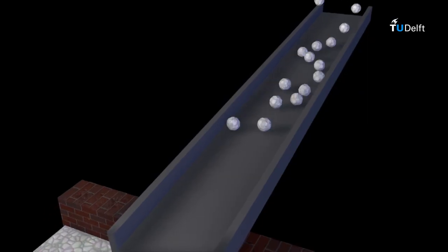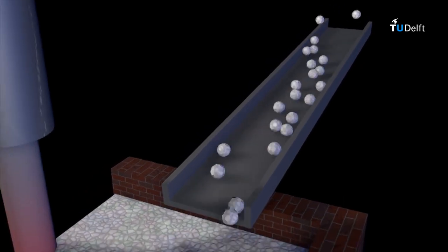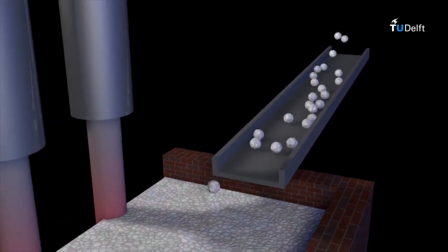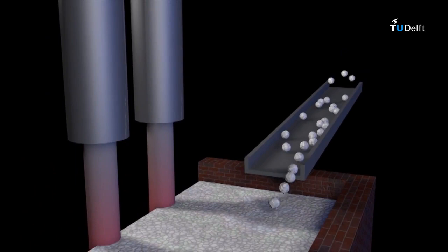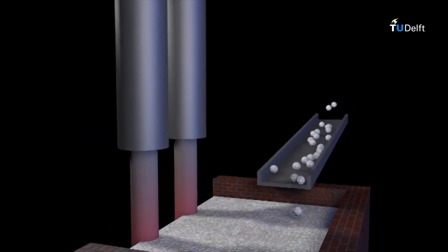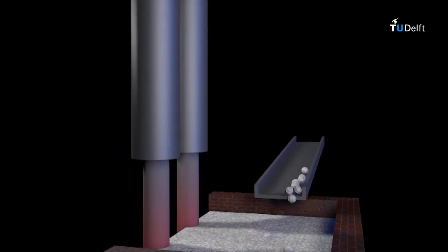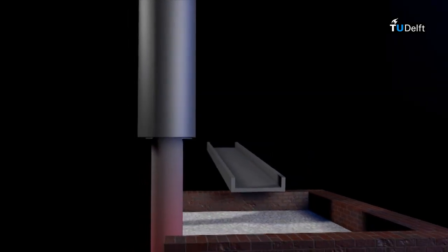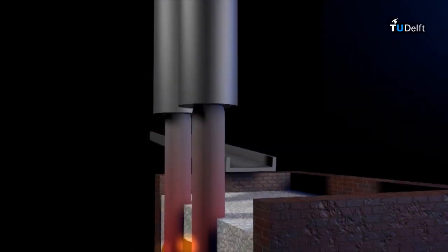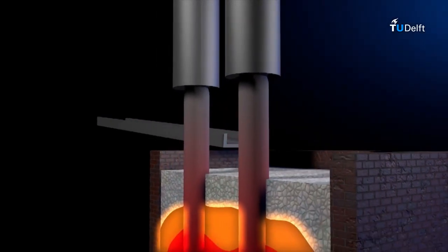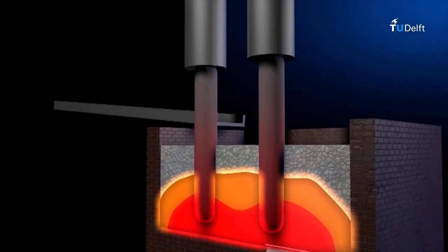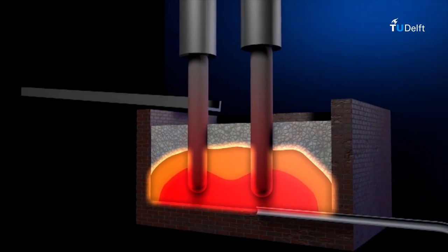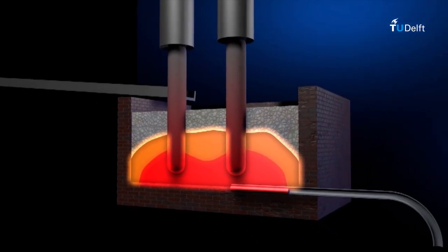During the production, the silicon is purified by removing the oxide. This happens in a submerged electro-arc furnace. The quartzite is moved into the furnace where it is melted. Using an electrode, the quartzite is heated up to a temperature around 1900 degrees Celsius. The molten quartzite is mixed with carbon. The carbon source is a mixture of coal, coke and wood chips.